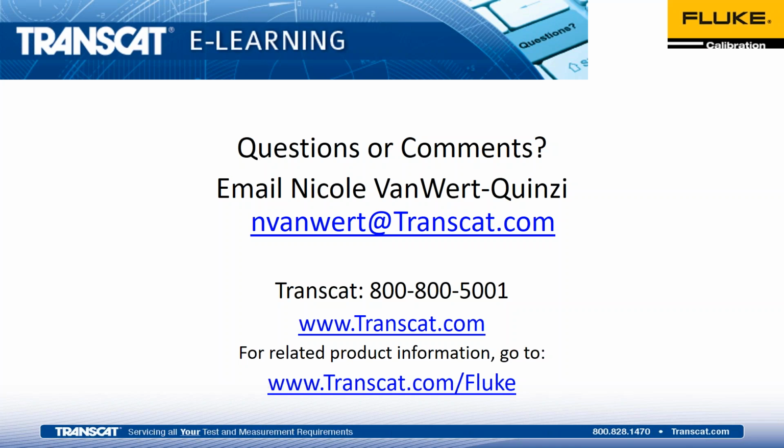All right, next question. Can I use a drop of oil in the well for better contact? I wouldn't recommend it. There are thermal pastes and grease out there, but unless the well is specifically designed for that, I would avoid it. What happens over time is that whatever makes the oil viscous or lubricating cooks off, and it becomes more or less like a glue. I've seen over the years many inserts get stuck or probes get stuck due to this.